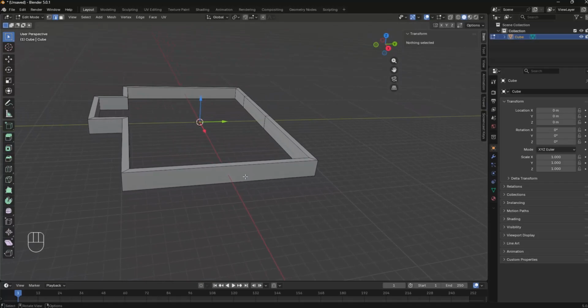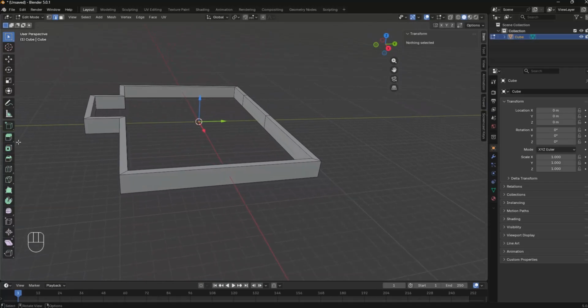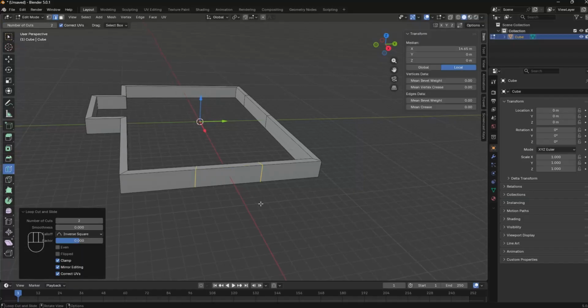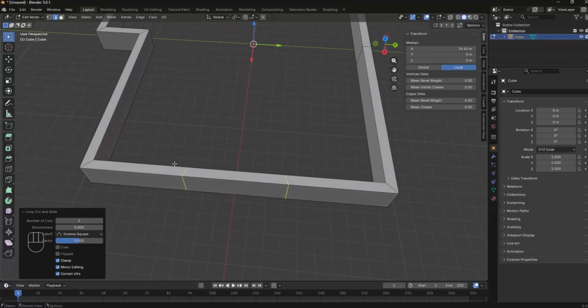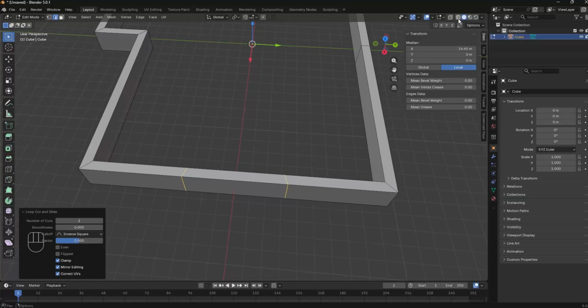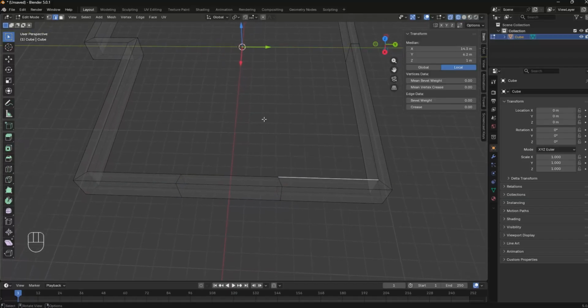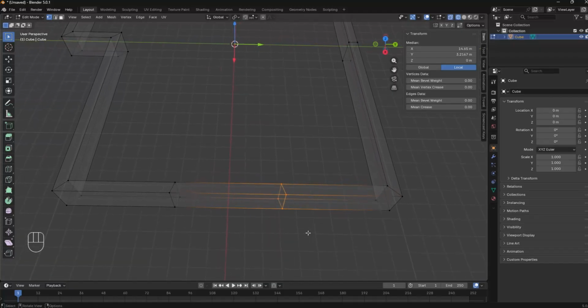Let's pretend that maybe on our foundation there's a doorway that we want to have someplace. We're going to go back to Loop Cut and do 2 loop cuts. But you can see that these loop cuts aren't square. So I go to the wireframe view. I'm going to switch to vertexes. Select all of that particular loop cut that I did.